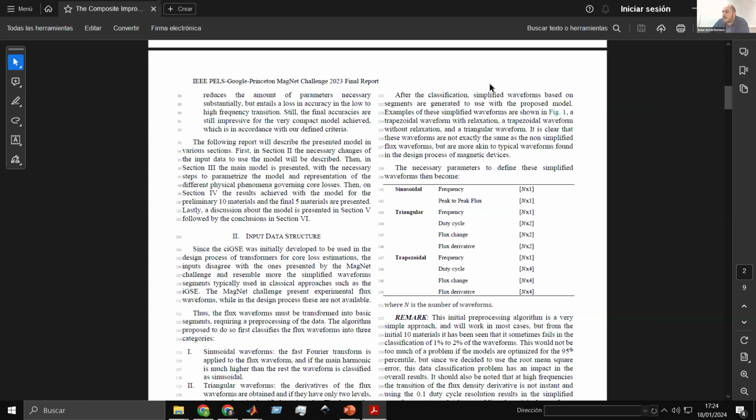And the good thing about this is that Steinmetz did his original work with iron cores. It's not a ferrite, it's iron, and he showed basically the same equations. So it appears you can maybe extrapolate this to even iron cores and not just ferrite cores. That's very interesting. But if you want to improve the accuracy, as I have said, there's a diminishing return in going for extremely high accuracy, because it's very good for this core, but what about this core? There's still a lot to investigate about how much error is average in a core. But if you combine this with a neural network, even a small neural network just supporting this could achieve really crazy accuracies, right?